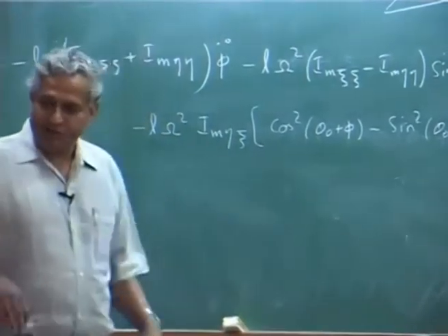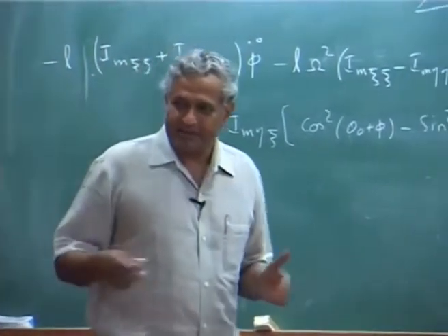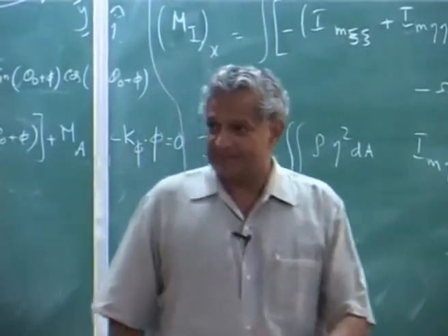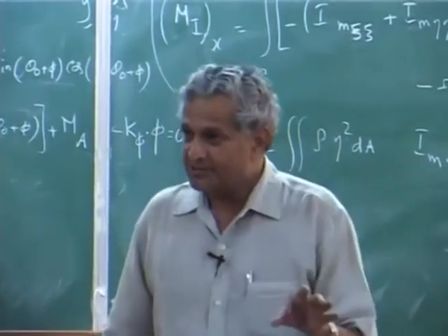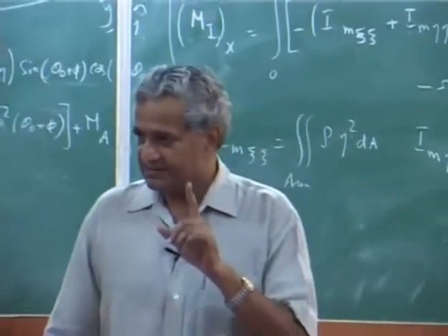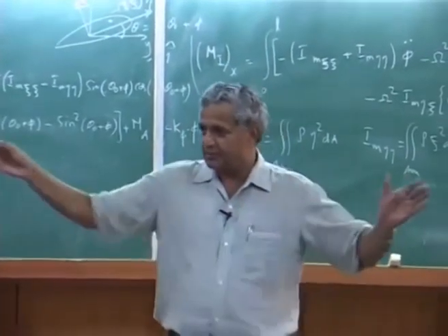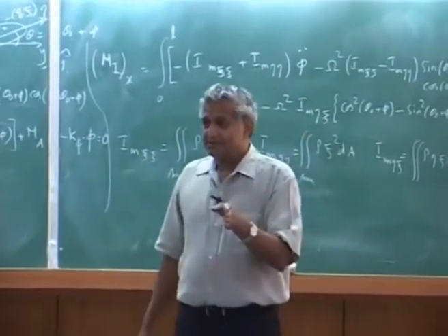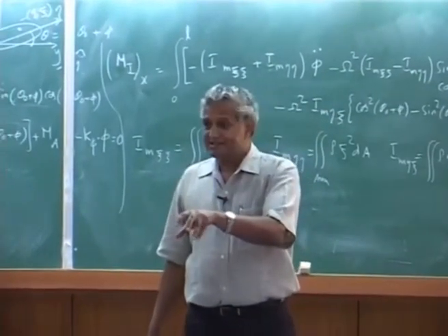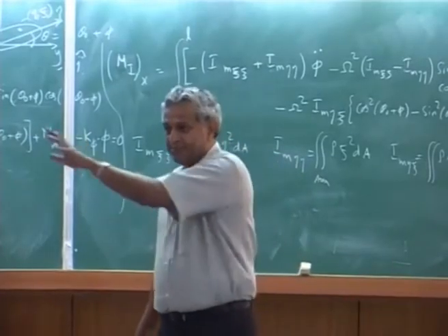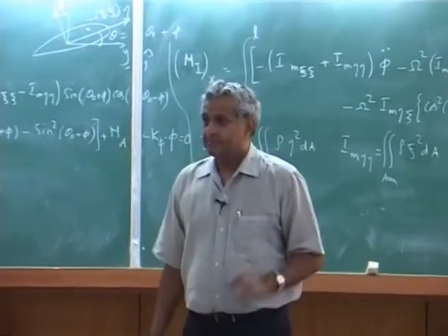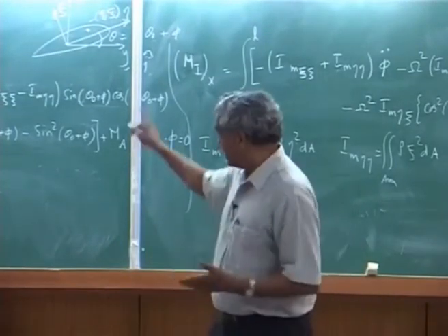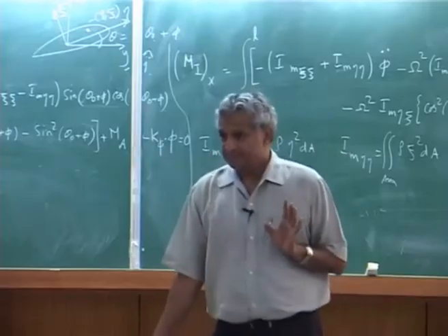Earlier, that includes, that is why I do not take it separately, because for the acceleration at a point, what I wrote, the big expression, it has everything, the Coriolis term, but omega is constant. You know that when you take a rotating beam, you will write the acceleration as four components: relative acceleration, Coriolis acceleration, angular acceleration, centripetal acceleration. That is for ease of things, but if you read this derivation, it follows everything, okay.